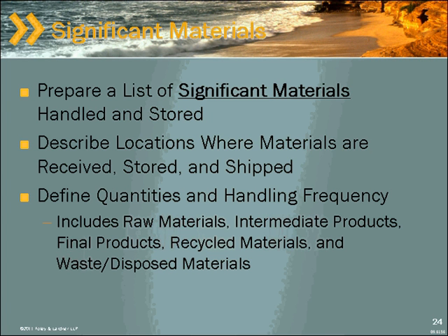Mm-hmm. Let me just comment on that, and this is just fresh in mind because I went to a facility just recently where this was the case. It was an industrial facility with a little bit of external exposure, but not a lot, and a stormwater management plan in place. But the owner of the facility had decided, for whatever reason, to bring his large motor yacht with fresh bottom paint on the facility and store it in the same area as his other outdoor storage, and the SWPPP did not, in fact, address that. Well, that would not be acceptable in this new permit in any way, shape, or form. That kind of storage of a boat with a bunch of copper bottom paint on it would definitely need to be addressed in the SWPPP if it was going to occur.